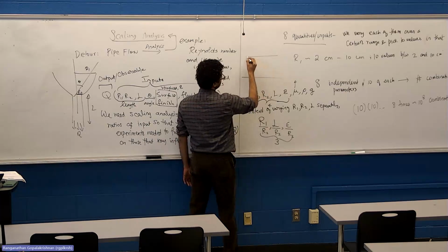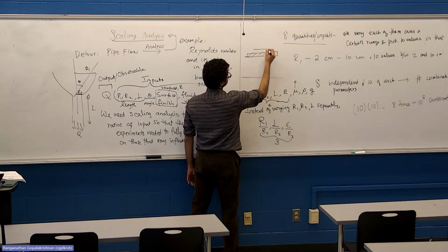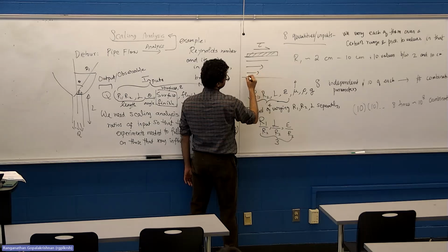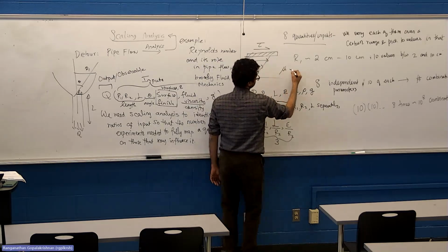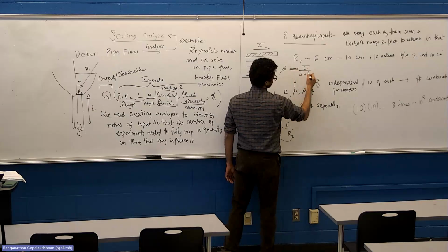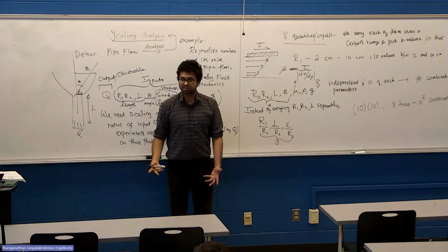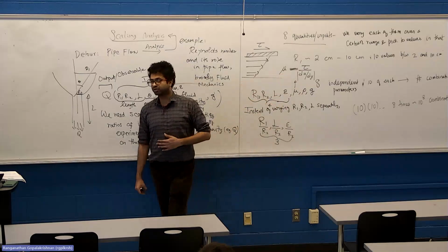So you have a fluid, let's say you have a surface and you have fluid on that surface. And if you apply a shear stress, you develop a velocity gradient. Okay. Viscosity is the ratio between shear stress and velocity gradient. If I tell you this, or if you remember this, or if you look up this, from here, can you tell me what's the unit for viscosity?